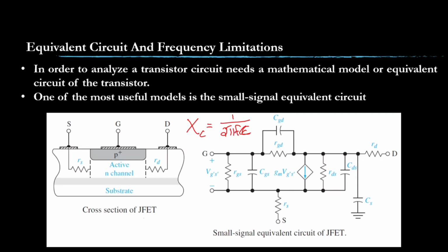So, now we are going to treat this circuit at low frequency. What will happen at low frequency? The frequency term is low, the capacitance is constant, 2 is constant and pi is constant. When the frequency is going down, what will happen to the reactance? It is going to increase. So, at low frequency, the capacitor offers a high reactance, that means high resistance to the current flow.